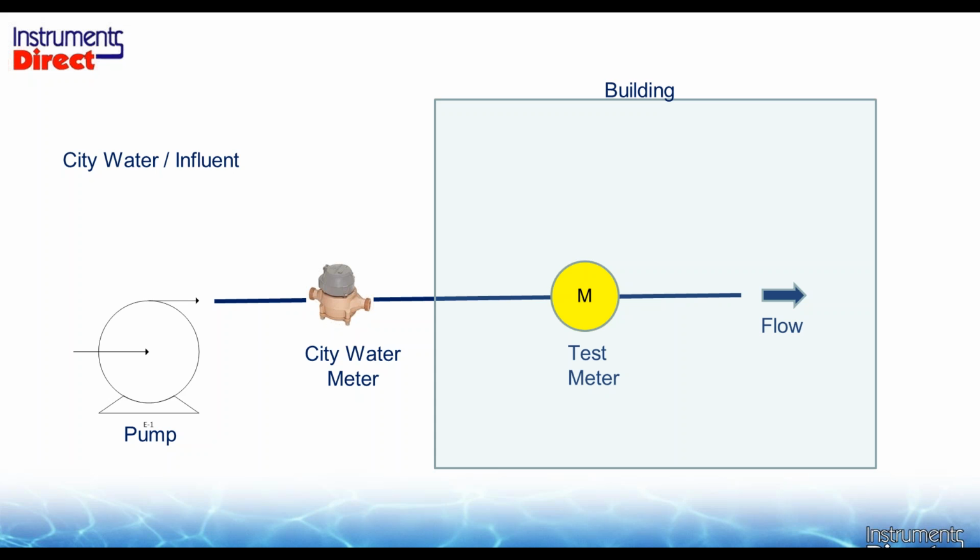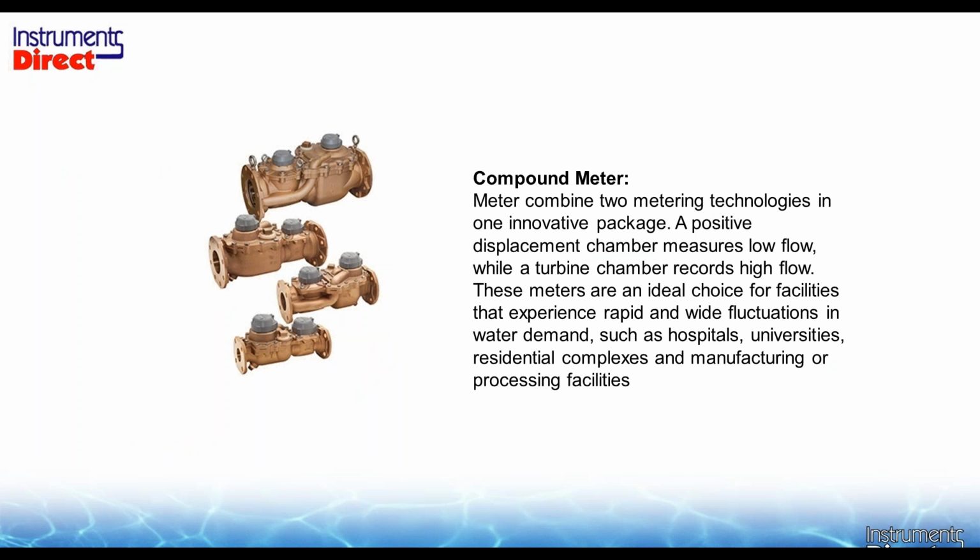How does the city do that? Well, they don't use a traditional 8-inch meter. In most cases there, they'll use a compound water meter. Now, a compound water meter is 2 meters. A compound water meter basically is a big meter and a little meter. And the little meter basically, what would we say about velocity? The smaller the line size, the higher the velocity.